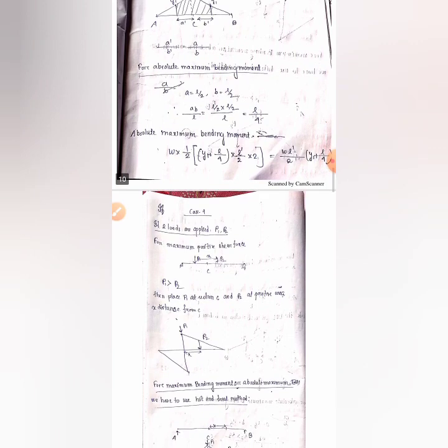UDL from the section C will be 2. Suppose UDL has the length, its span over 5 meter. Okay, then it will distribute at 2 is to 3 ratio. That means 2 meter from left and 3 meter from right. That means the ratio will be same. Okay, so now we can find the maximum absolute bending moment here.